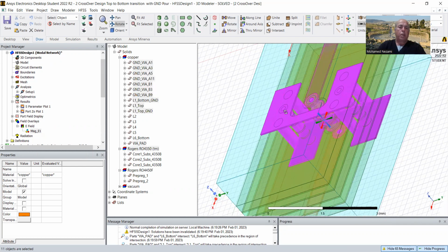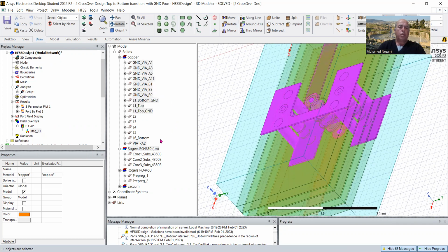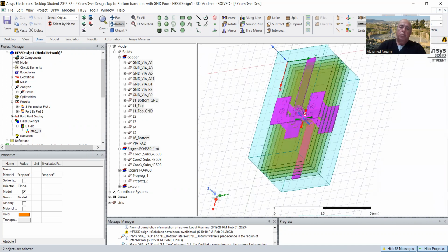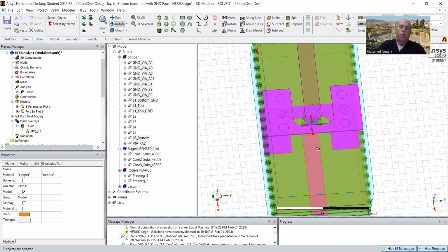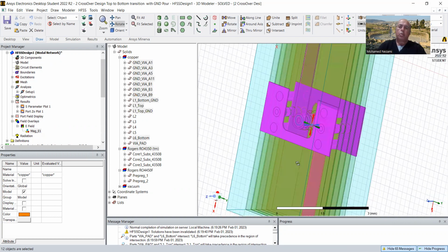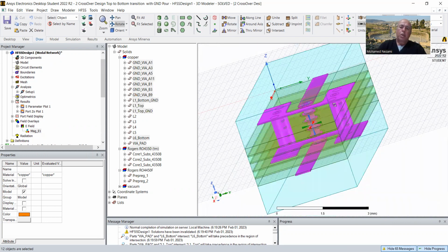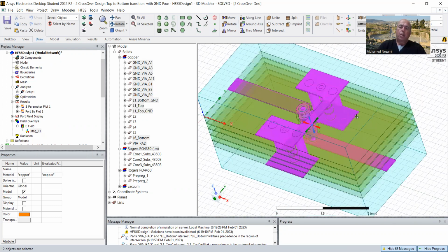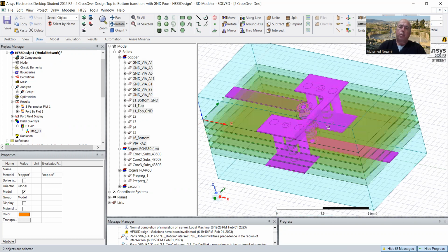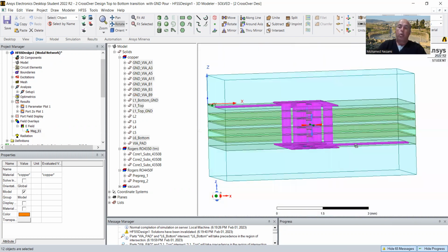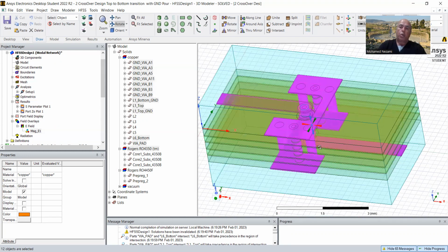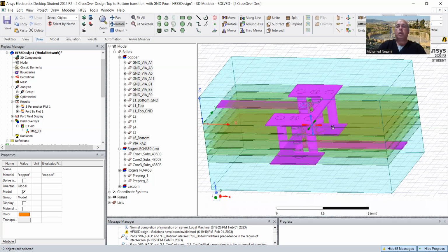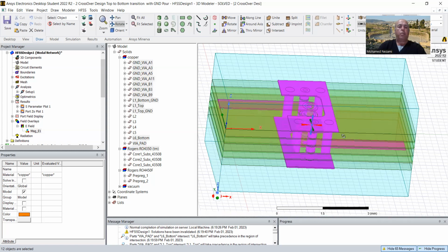Okay, and then the other side, let me get the other side. So you can see these metal pieces in here are all working together to make sure that the signal is preserved to stay only in this area, so that you can come in from the top to layer 3 or to the bottom in this case, but cross over and go through, clear from all layers and end up in the bottom without any interference.